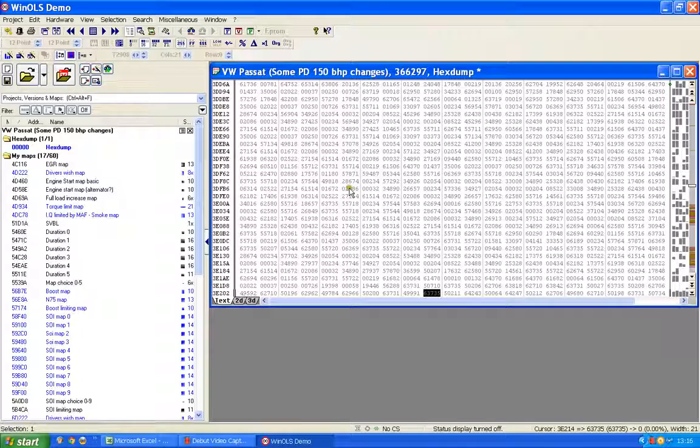So I'm going to look at possibly making some file changes. I'm going to look at some EGR changes, because people do tend to want to do that. I get asked regularly, can I blank off the EGR? And I say no, because if you do, you'll get fault codes. And then the next question someone asks is, if I get fault codes, can I switch them off? So it seems a sensible thing to put into a video. I'm not suggesting that people should blank off EGRs, and I'm not suggesting that if they do, they should reset fault codes, but this is something that can be done.